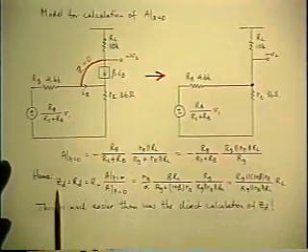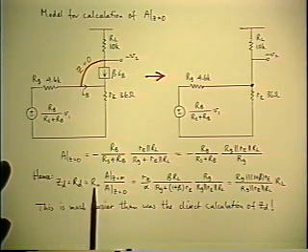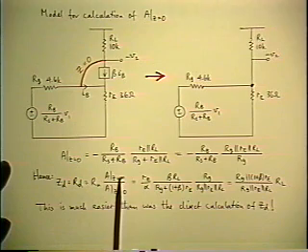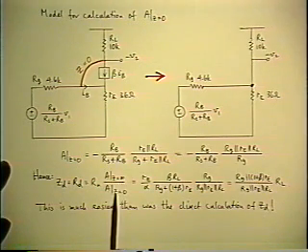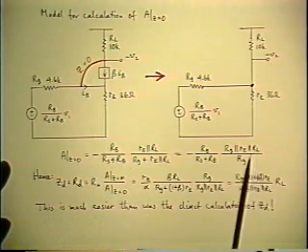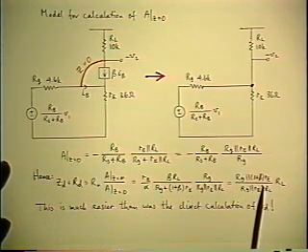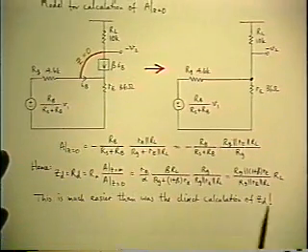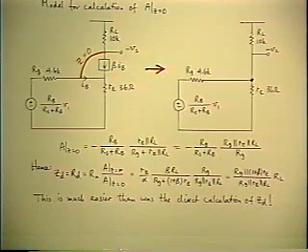So then, using the redundancy relationship to find Rd, it's equal to the Rn that we know already, multiplied by the ratio of the midband gain that we started with, divided by the gain when Z is 0 that we've just calculated. And there's the answer, which is a lot shorter than that long derivation with the circuit reduction and then still quite a few lines of algebra to deal with.